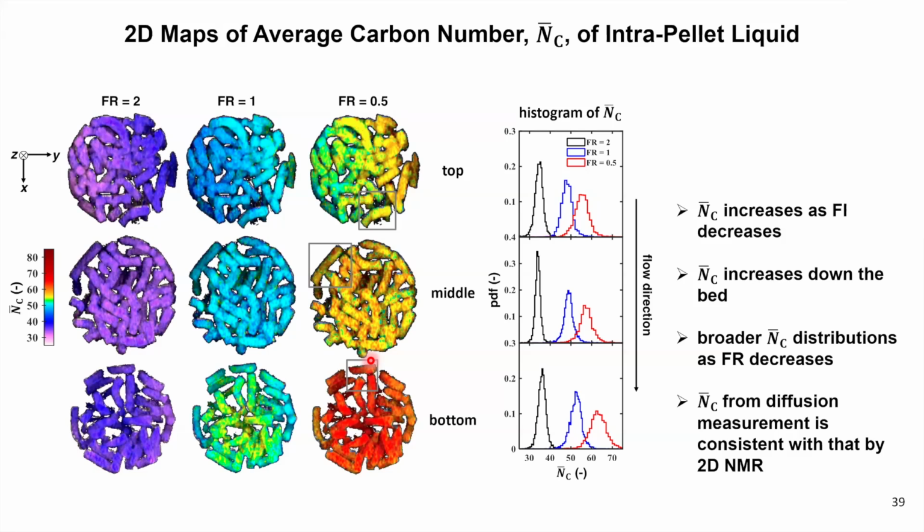But essentially, you're producing this liquid, and as the reaction progresses, you're producing more. It's being forced out of the pellet, and then three things are happening to it when it comes to the outside of the pellet. One is it's vaporizing. Right, so we have a range of different chain lengths, and those below sort of C10 will largely vaporize, depending on the partial pressure of those within the system. You'll have some, particularly the shorter chains, will be flowing straight out, just under gravity. They will be falling to the bottom of the reactor, and that's where we collect our product.